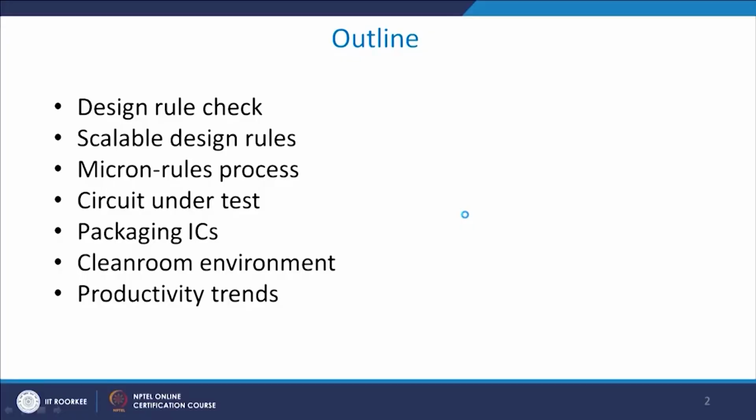So, I will give you certain design rule checks, also known as DRC. So, it means that once your design has been done on a simulation platform, your layout has been done, you need to check, for example, whether the width of the contact which you have drawn is as per the requirement of the fabrication facility, right. So, it might be true that a fabrication house can only make a contact which is, say, in very layman language 1 millimeter by 1 millimeter, and you had made 2 millimeter by 2 millimeter. So, it will be rejected once your design actually goes to the fab house.